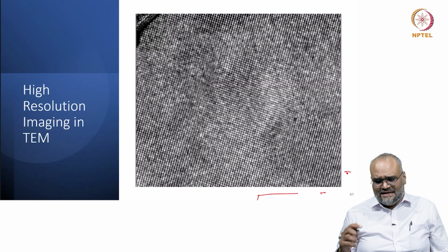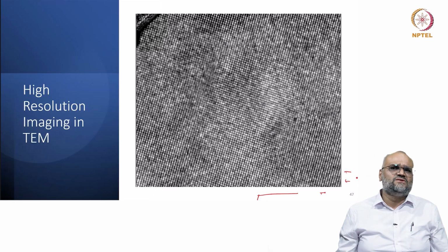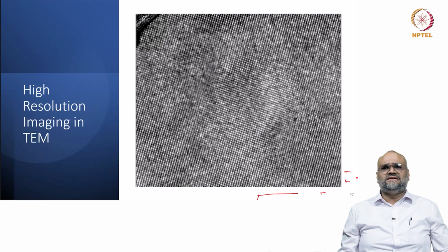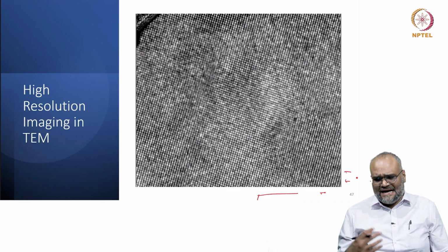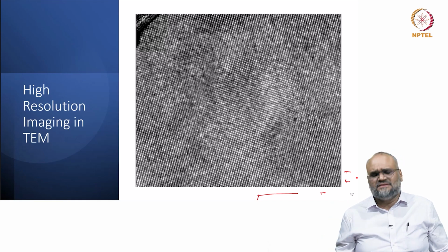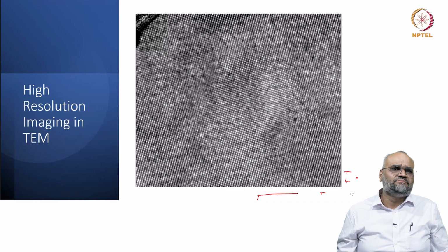Primarily you have to check the diffraction pattern and orient the crystal into the zone axis. We discussed this in the demonstration sessions, and once you orient it into the crystallographic zone axis and do all the primary corrections, you can then start imaging and get information on the high resolution from that particular material.